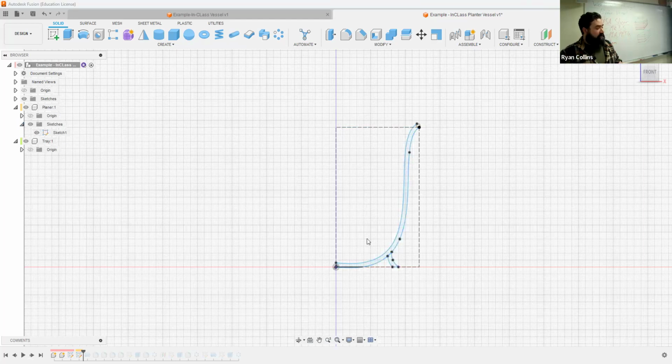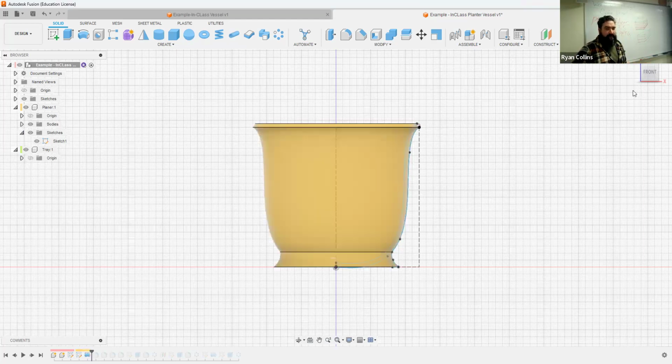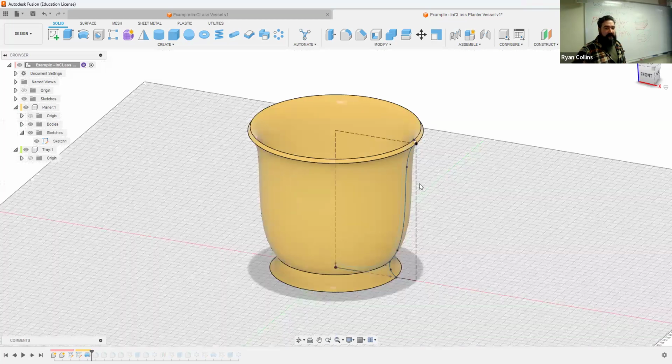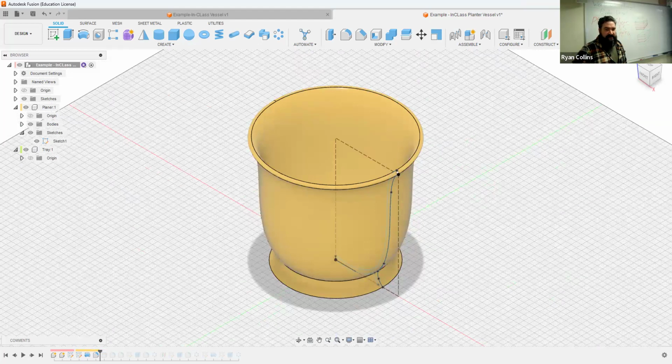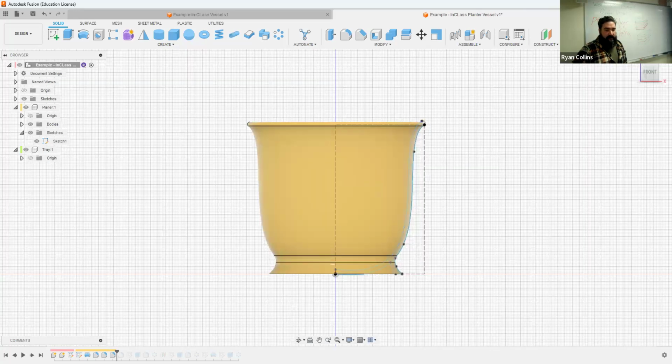Simply that. We're going to be using the offset tool, probably, that sort. From there, using the revolve tool, bam, instantly rotates that sketch around, and you create a shape, a rounded shape. How you go about it, more or less up to you, so long as it's a sketch and using the revolve tool. Now, I made some additional features, fillets, just changing stuff around, added some features on the bottom, adjusting the profile here, adding more and more.